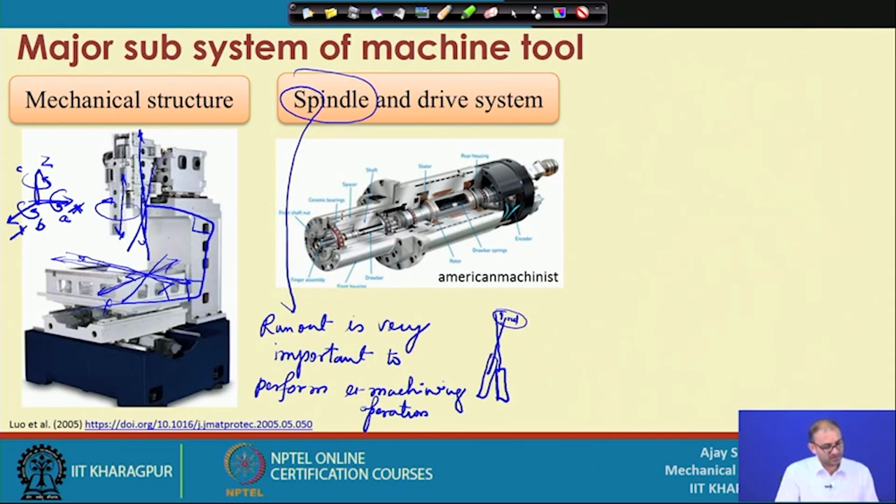So, spindle and drive unit. What you are using for driving this spindle is also important. That means the frequency response of that, how quickly you can reach the spindle speed. There are vector control spindles available, so that every time you stop the spindle, your tool is always in the same direction from where it started. Those things we will see in the different spindle systems.